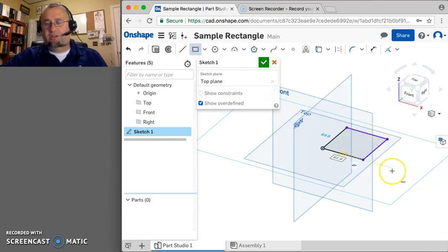We would like to constrain all the lines in our sketch so that they're all appropriately defined. So the way to do that is I'm going to add some dimensions. And notice here, I again just arbitrarily let go of my mouse at this point. This dimension is 61.9. That's the length of that highlighted leg of my rectangle. This guy is 63.9. That's the length of this highlighted leg of my rectangle.